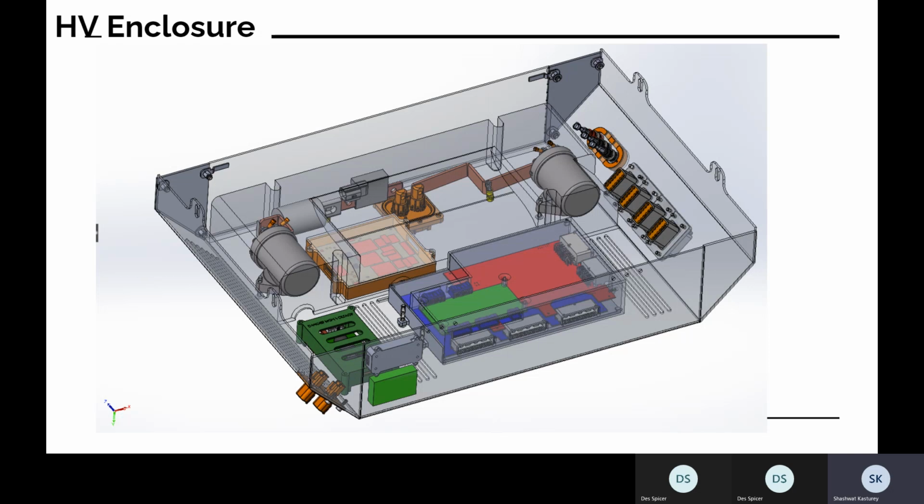This takes all those 96 signals, or however many it was, 21 times 6, and turns it into 2 pins rather than 96. So it can report that to the VCU, and the VCU can decide what to do with that information. If a battery cell gets too hot, the VCU shuts the car down. If the battery cell is too low in voltage, the VCU shuts the car down.